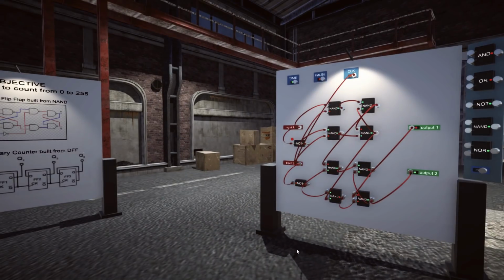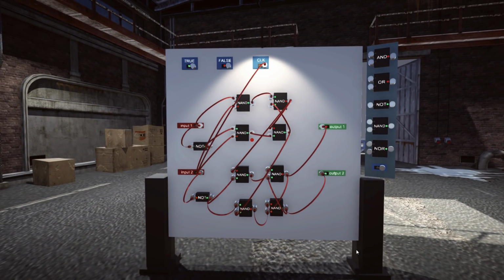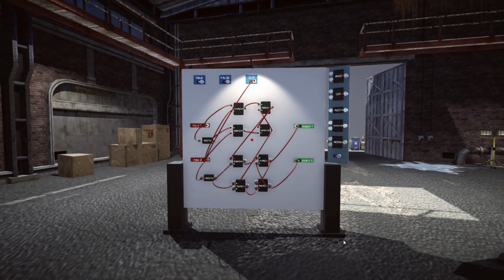Yeah. I mean, I've finished the first puzzle there, and I've tested it. It's definitely working. So this is essentially latching a value. So it's like a delay. Think of it as like a delay circuit. If you send a high signal in, one clock pulse later, a high signal will pop out the other side, right? And that is how we're going to do a counter.